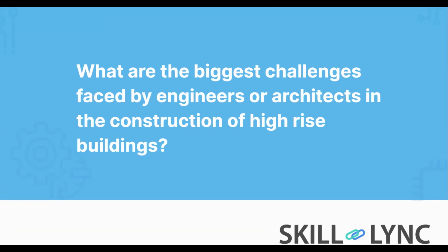And also in terms of reducing the load, we try to go for lighter materials. You need concrete with higher strength. Generally, for small buildings, you will use like 40 or 50 or even 30 Newton per mm square. But for higher buildings, it will be 80 or 90. So you need the technology to prepare this sort of high strength concrete, and to deal with all these issues on site in terms of workability, etc. So all these things are challenges in terms of construction of high-rise buildings.